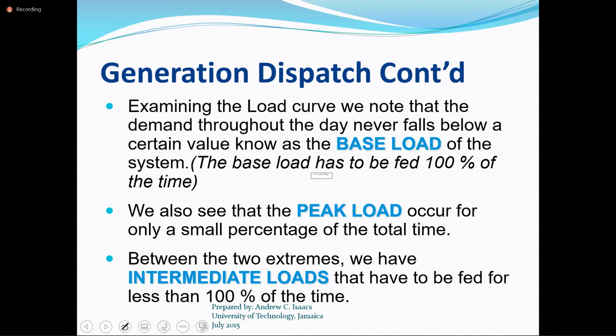one of the main purposes of your slack, and the name really speaks to what it's there for, is really to provide voltage stability. And to do that, your slack generator is going to produce additional megavars into the system.